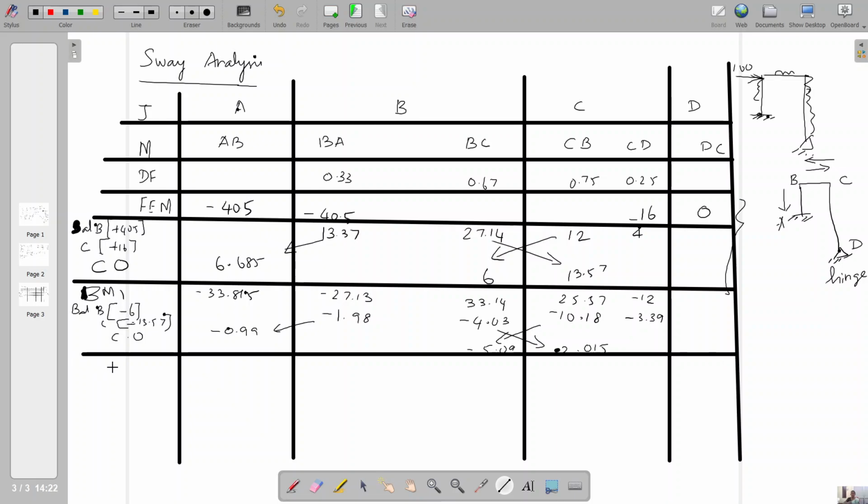Again, we calculate for the second trial. So we have completed the second trial. Bending moment 2, you get minus 34.805, minus 29.11, 24.02, and 13.375, minus 15.39. Here the 0 exists throughout. Next balance B, the moment of 5.09, and C with a moment of 2.01, unbalanced moment.